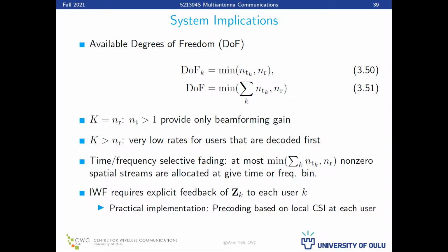Naturally, so for example, in this case, if we had, let's say, 4 users, and relatively high SNR, so all 4 users, if they ignore the interference, they would send 2 streams, right? If they are not constrained by anything, they would assume no interference. There are 2 degrees of freedom, high SNR, assign 2 streams. So in total, there would be 8 streams and just 4 antennas. That's inefficient. It still works, but these extra streams will have very low rates, right?